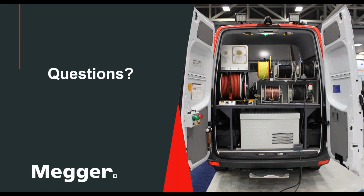So anytime you send high voltage out, you must observe that protocol, because otherwise you might be sending high voltage to, for instance, a low voltage circuit with a meter box connected. If you fault locate and send 1,000 volts down that cable, you would blow everything up in that house, right? So you must be isolated. The moment you use high voltage, you must use isolation on the far end, and on the front end it's also isolated because you're connecting your equipment to it.